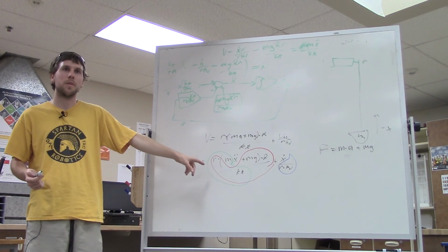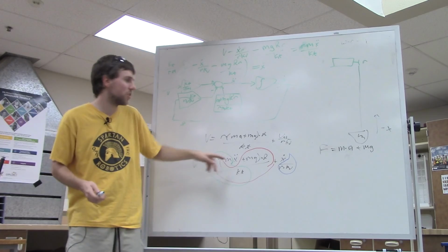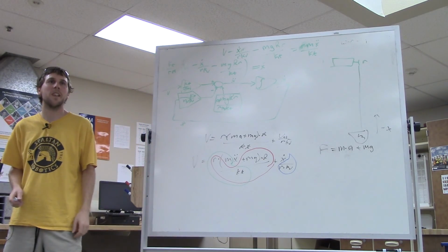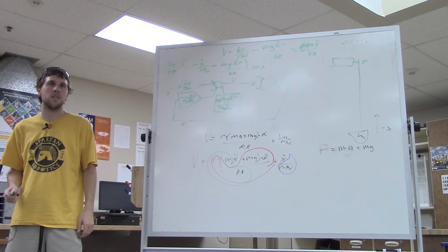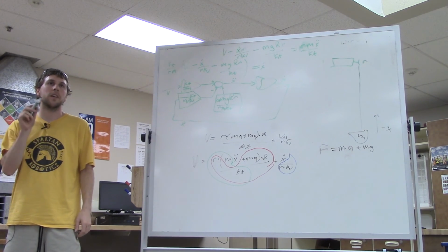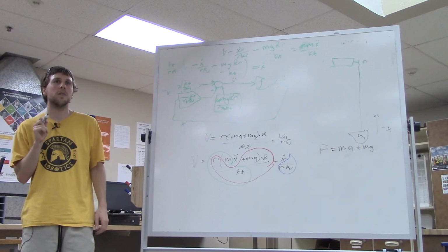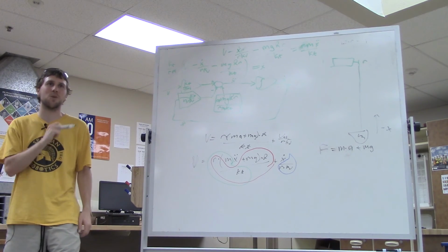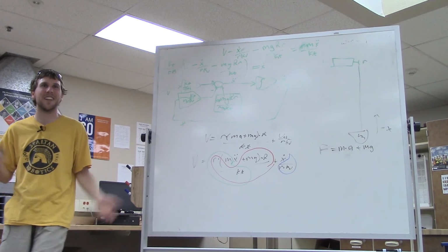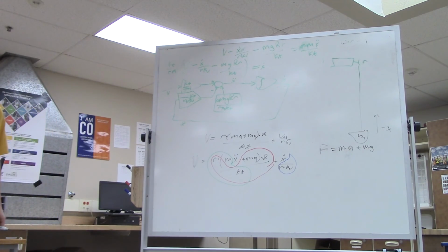It's a nonlinear system. So generally what we like to do is try and linearize it. So we try and just offset gravity. Well, why couldn't you just use this equation to predict what voltage you need to input into the system to get the desired output? You're assuming you're getting an LTI response out of your system, and that breaks the assumptions that all the controllers are designed with. So none of the math holds to design the controllers. Okay. Which is a pain in the rear. So, I forgot about that.